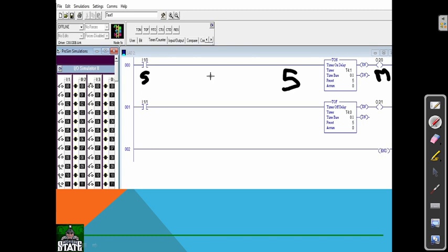We can use this in industry. In some particular places we need to start the motors or start the process some time after we press the switch. That will happen over here. This is the on delay timer. Then we will move to the off delay timer.